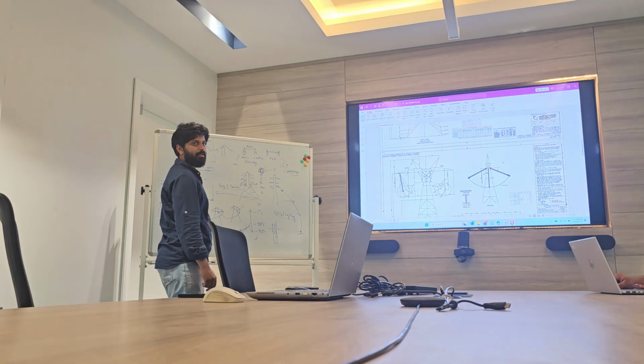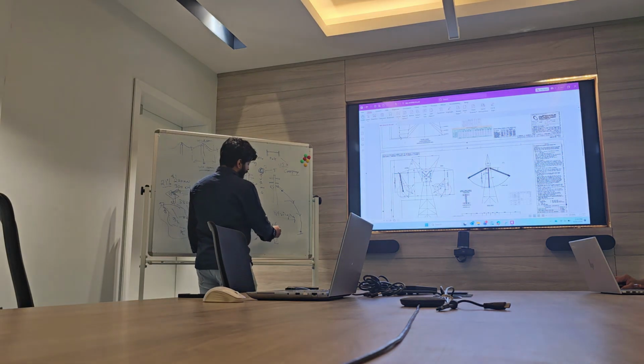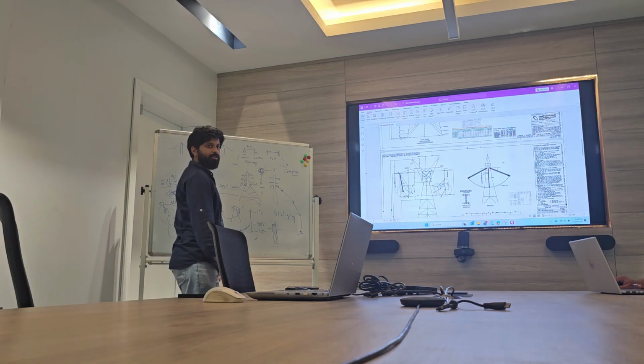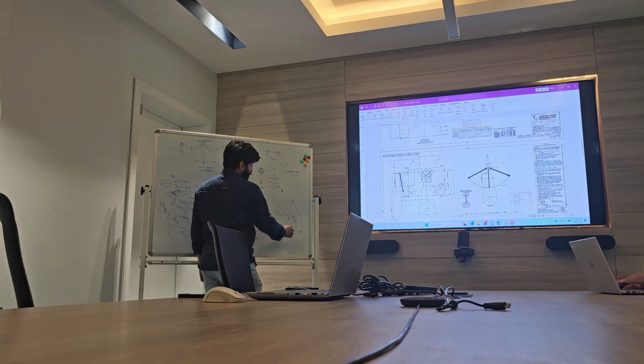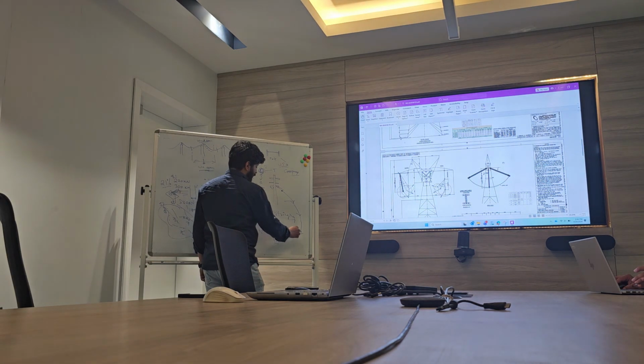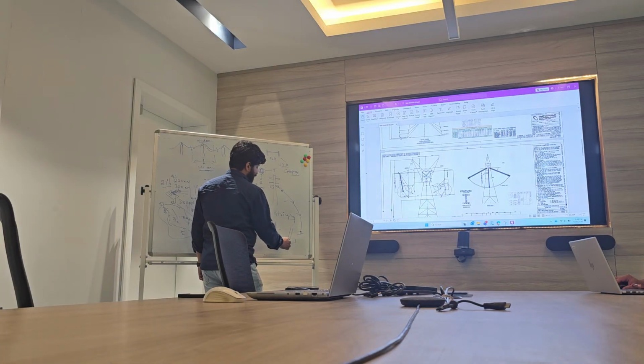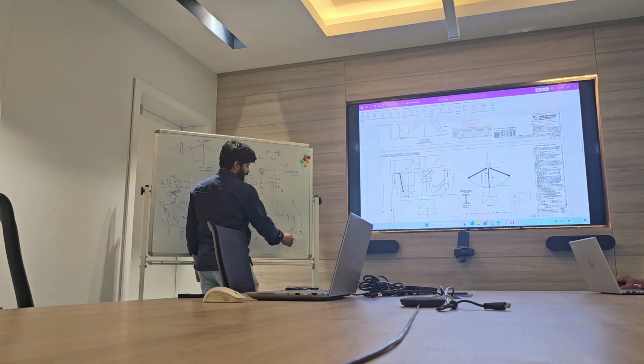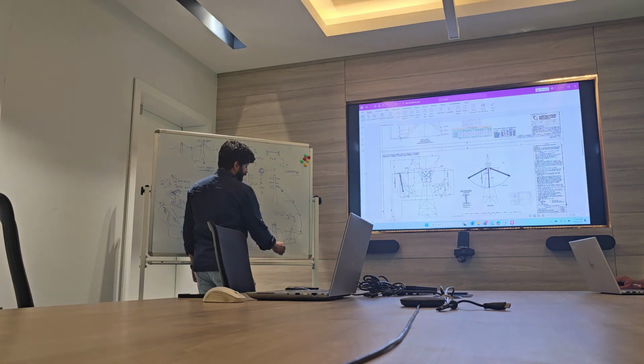Pile or auger foundation. Yes. Okay. Sometimes no need to put the stuff inside. You can put a base plate and anchor bolts. This arrangement also is there. Besides pile and auger foundation, we also have another type of foundation, where we put the stuff inside and make it big like this. This is called pad and tube.